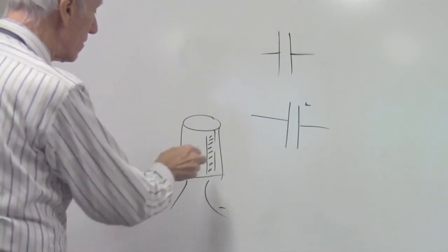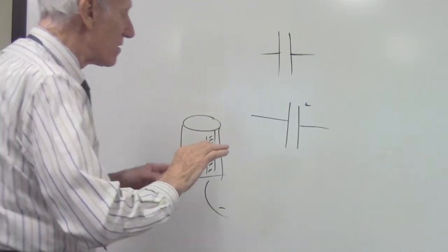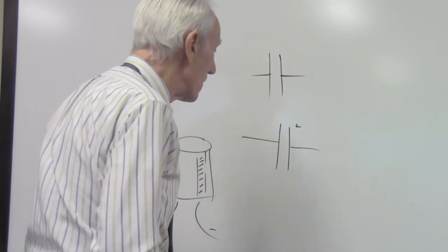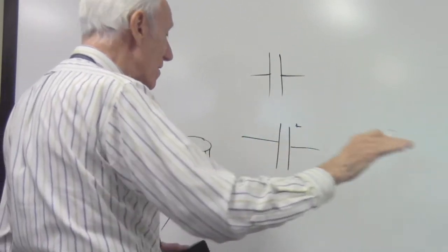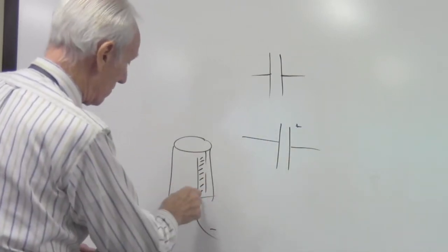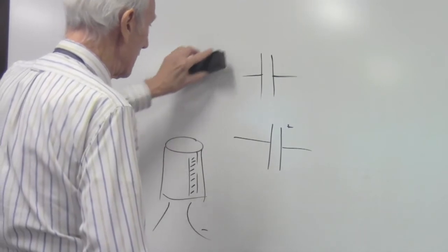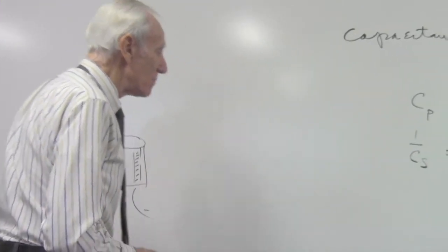So be sure when you hook them up that this band is pointing towards the ground direction of the black wires on your apparatus. If you hook them in series, make sure each one of their negative terminals is pointing towards the black lead. Okay, so that's our setup.